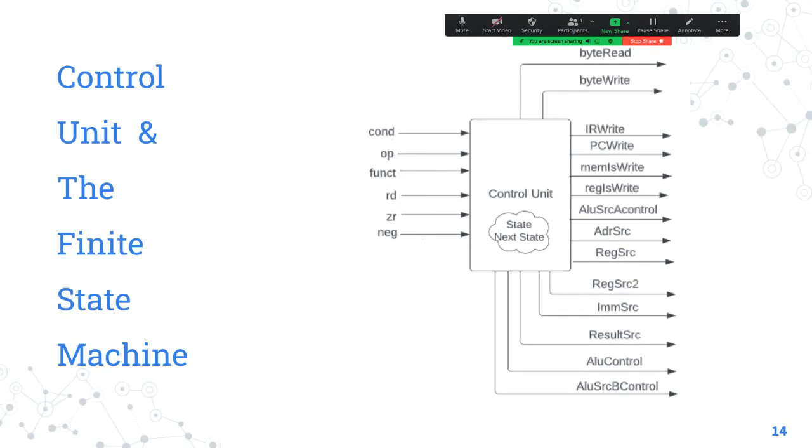That's what a multi-cycle processor is. A multi-cycle processor will take a different number of cycles for different types of instructions. When you design a pipeline, the logic will become complex. You will have to have multiple control units. Control unit will be divided. If there is only one control unit, at each time only one instruction is being controlled. If there are many instructions, each instruction will have its own FSM currently working. So that's what you will be doing. According to the current state and next state, you will be setting these flags and then working accordingly.